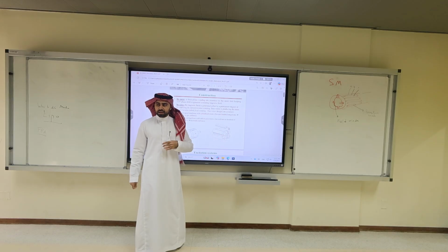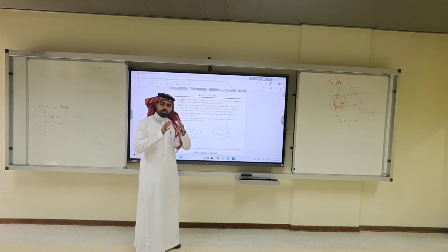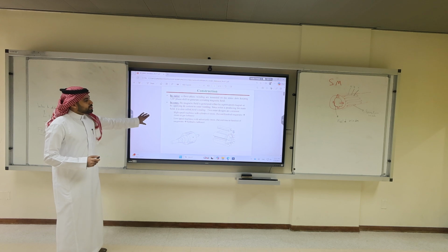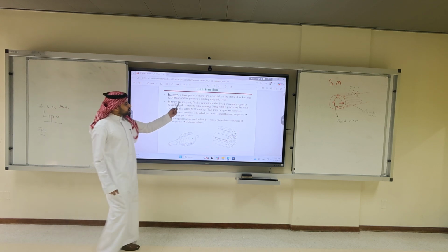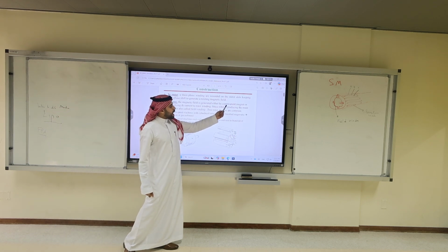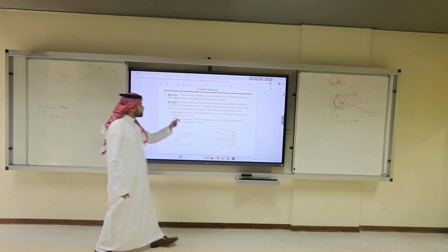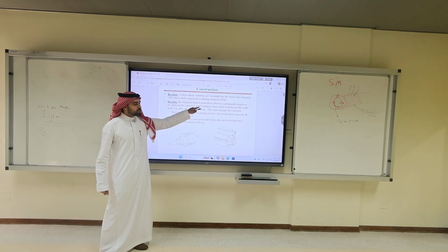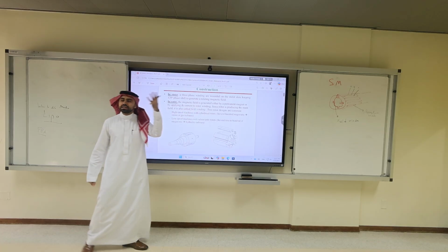The most practical, more affordable solution is that we magnetize the bars themselves. So in the rotor, the magnetic field is generated either by a permanent magnet or by applying DC current to the rotor winding. Why DC?